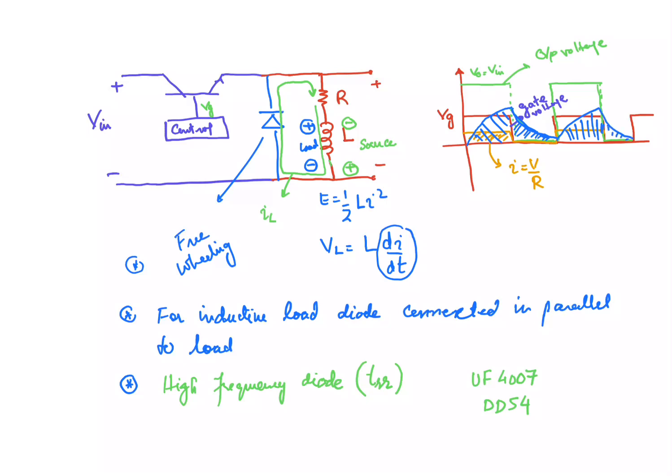And if your inductance is quite high, so what will be the current waveform in that particular case? So if your inductance is quite high, so current waveform will be like that. It is never going to come to zero, rather this is the minimum value and this is the maximum value. It is changing between them. So you can say that your current is continuous. So continuous current means that it is not going to come to zero in this cycle, and that is only possible if your inductance is quite high as compared to the resistance in your circuit, you will be having the continuous current.